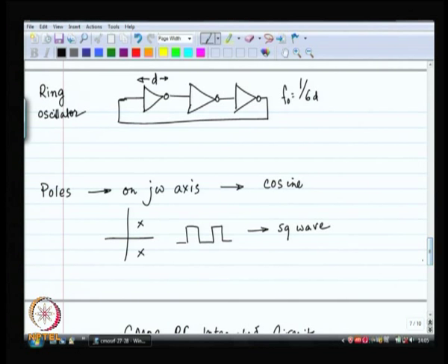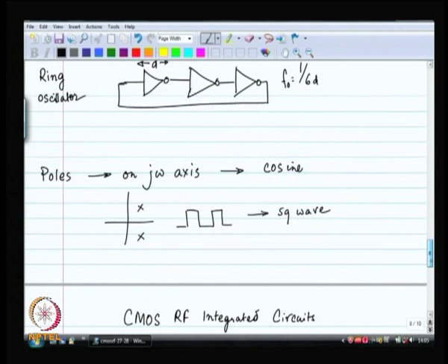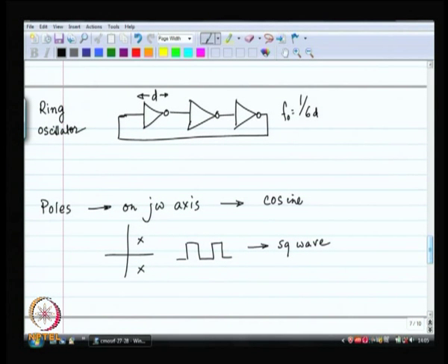We also picked our brains and reminded ourselves that there exist other forms of oscillators as well, ring oscillators. You can even design your own with poles on the j omega axis or outside on the right half plane, right. So, it is possible to do such stuff. You can also go for a different class of oscillators. So, there exists a second class of oscillators called relaxation oscillators.